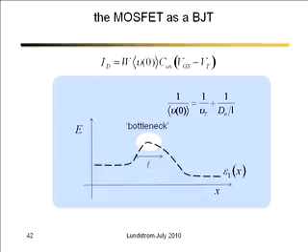Okay. Now, there's trouble. If L gets too short, diffusion is random thermal motion. You can never diffuse faster than the thermal velocity, because you're undergoing a random walk as carriers are just thermally diffusing. So if L gets too short, the maximum velocity that you can go across this region at is this ballistic injection velocity. And this expression just makes sure that in the two limits, you approach the right limits. Actually, it works in between, too.